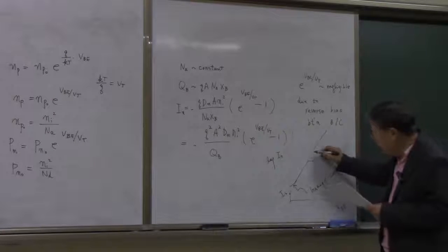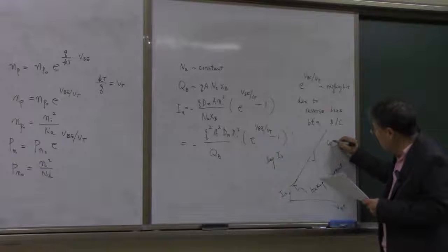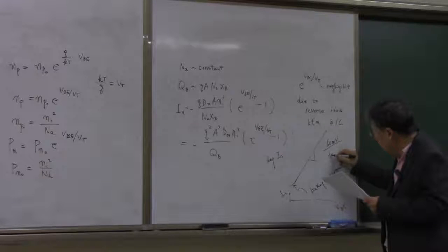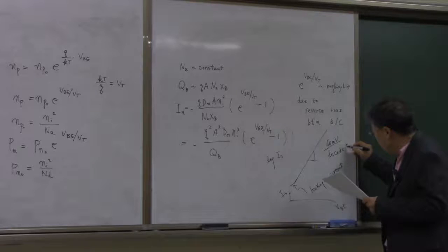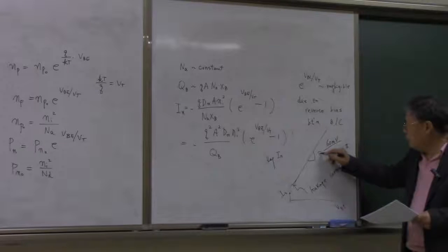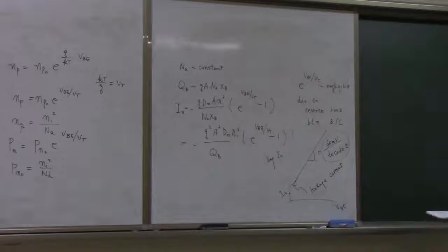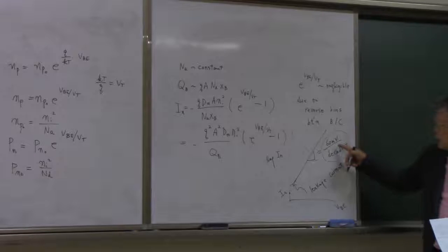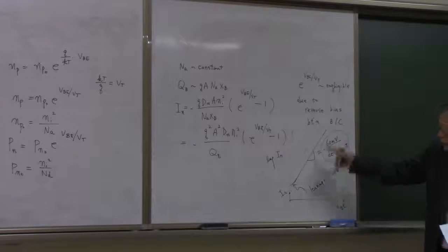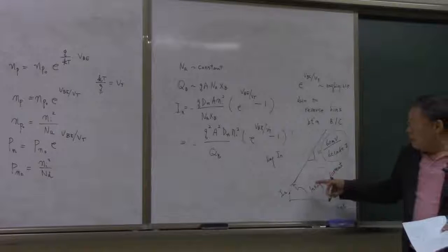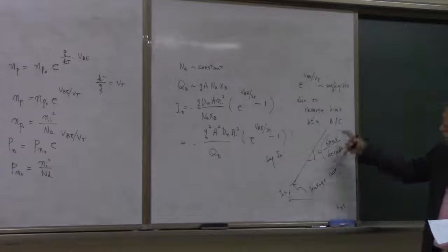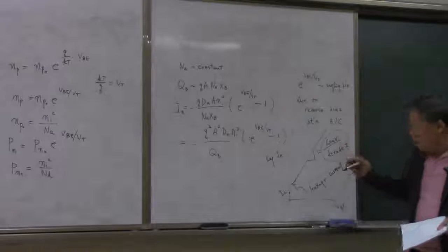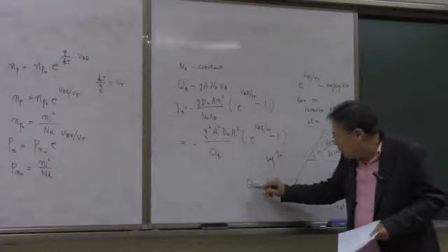And the slope here is about 60 millivolts per decade of current. This value is a very good value. In MOS transistor, it is very hard to get these numbers. Last time, in the ideal case, we have 60 millivolts per decade as a slope in the switching. But in a bipolar transistor, it can be easily achieved by making QB very small.